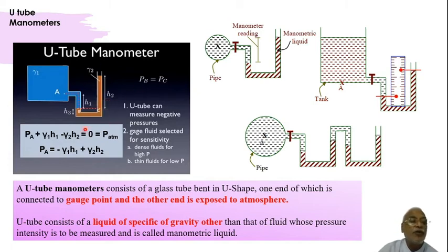Now the point to be observed here is, here there is water which comes and stops. Here the gamma 2 or liquid 2 starts. Now at point B and then at point C, we have the same liquid if you consider the bottom portion, and because of that, pressure at point B is equal to pressure at point C. That's what is written.